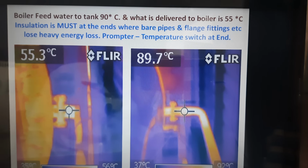So, this is a boiler case study which we did during our audit. We found the boiler feed tank is receiving water at almost 90 degrees centigrade, but insulation is not there from the feed tank through the pump up to the boiler end. Ultimately, the temperature at the boiler end, as you can see in the thermal imagery, is only 55 degrees. So, a heavy drop of temperature is happening because the pipes are left bare.